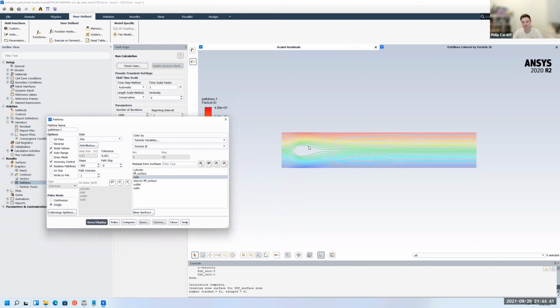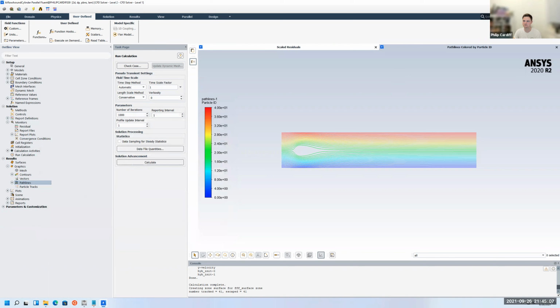So we can't see it here, but there's actually 2 smallish counter-rotating vortices that form just behind the cylinder. And so the shape of those and shape of flow are dictated by the Reynolds number. So in this case, the velocity profile that was selected was to cause this laminar flow with vortices behind it. So when you look at higher velocities, then you get vortex shedding and other interesting phenomena. So we just close out of this and accept the defaults.